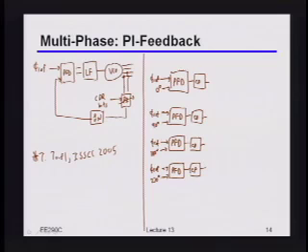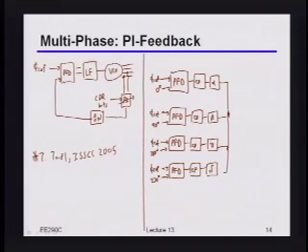And now if I just take those charge pump outputs, scale them by different weights for each one of those phase frequency detectors, and then just add all those things together in the current domain, and of course feed this through my loop filter and then into the VCO, which then generates those 4 phases. Well, now by changing those coefficients, I can have the same effect as doing that phase interpolation.